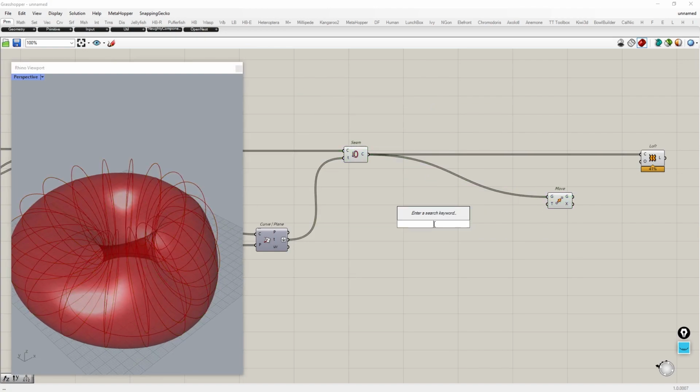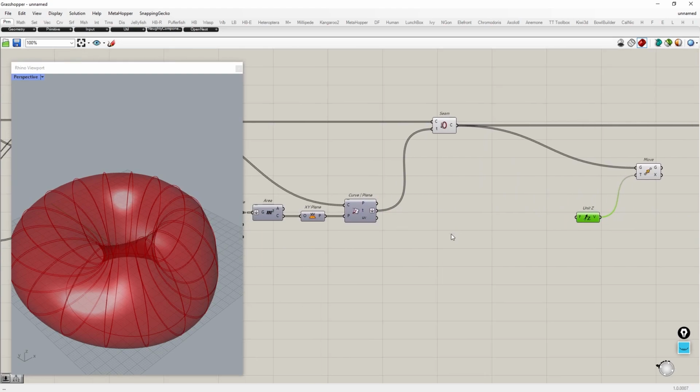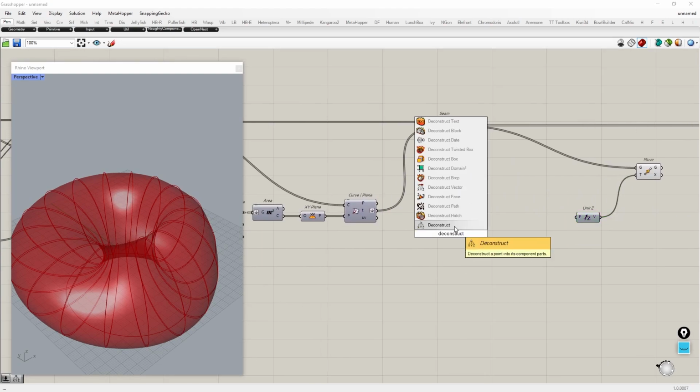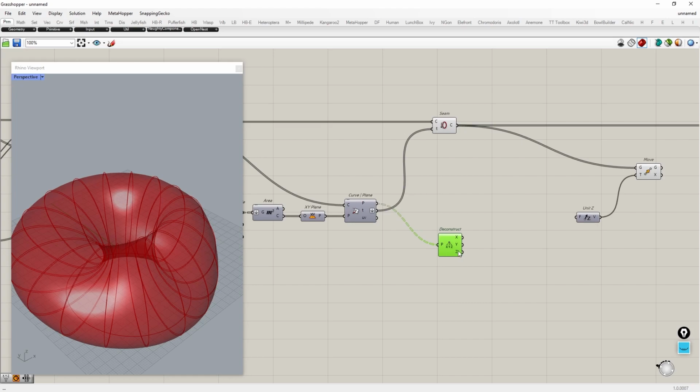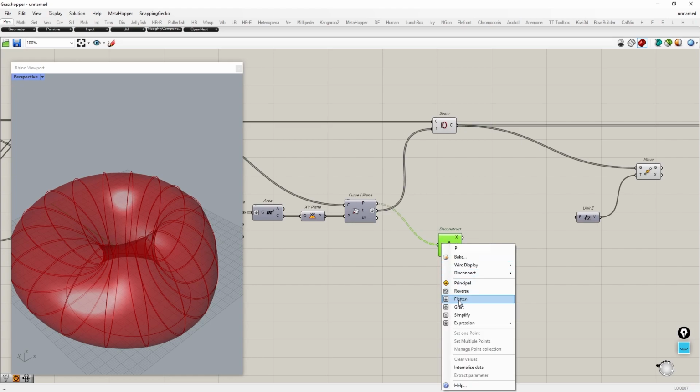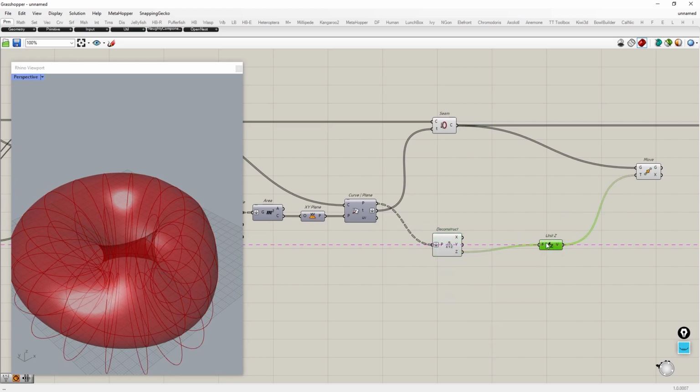Next, move each ellipse in the z direction until their base reaches the xy plane. We can use the z coordinate of the intersection point. This gives the distance below xy plane. It's a negative value, so add the expression -x to change the sign.